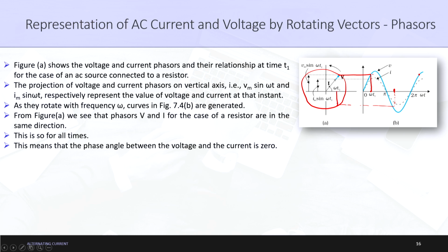So after this complete cycle is obtained, from the start, let's say t is equal to 0 and t is equal to T, that is the complete time, you can obtain that this complete circle diagram is being created. So that's how a phasor diagram actually works. Just explaining how to make this phasor diagram. Let's say you need the answer at some time t1, just drop a perpendicular, and then on this virtual circle, pinpoint that location, and that is the location of the vector of the phasor diagram at that time t is equal to t1.